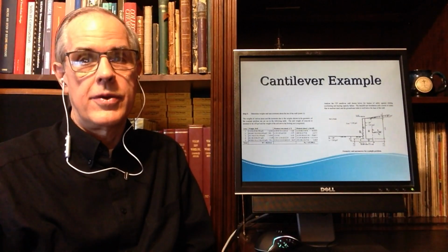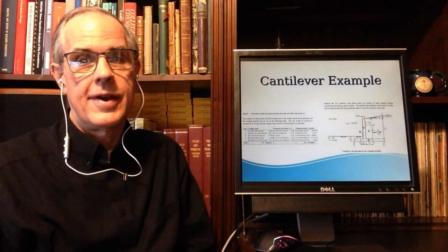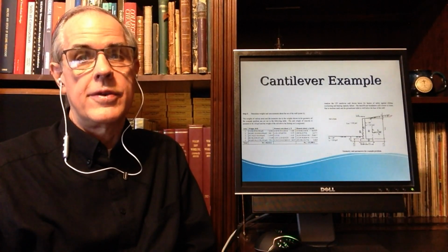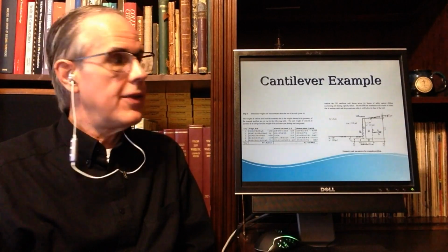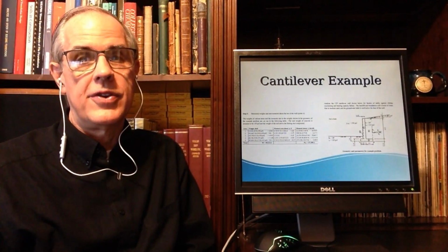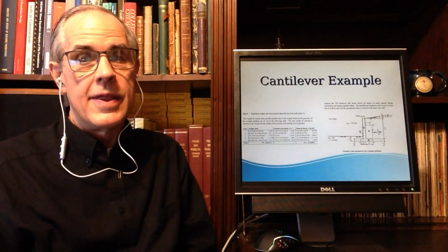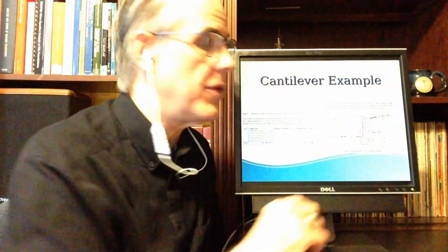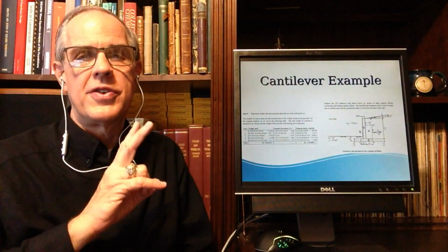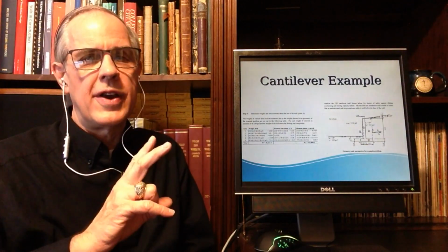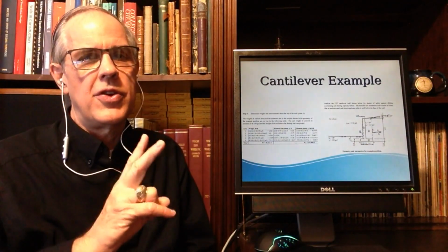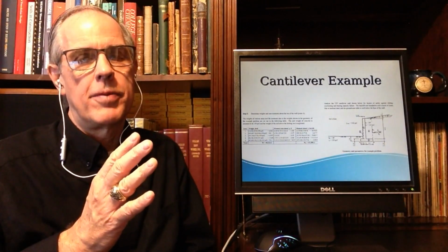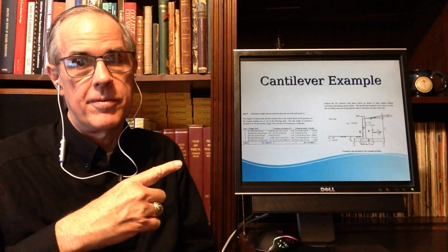There's another way you can do this as well and save yourself a lot of time and trouble, and that way is to use your CAD software. If you laid this out in your CAD software, which I suggested earlier, that reduces you to 2 different areas, because you've got 2 different unit weights. You can't combine things that don't have the same unit weight for the purposes of this calculation.